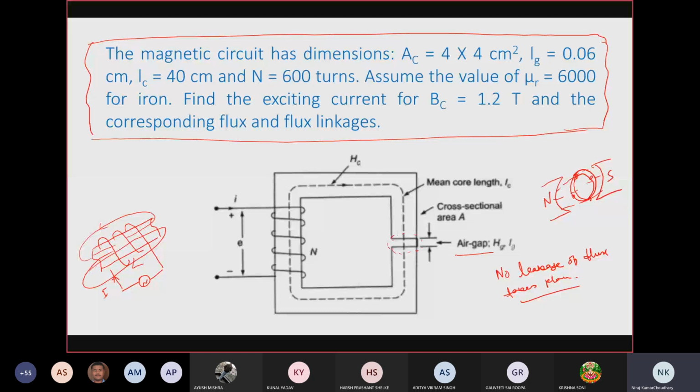through that conductor. So flux will be there, yes, but the amount of flux practically will reduce because air will have a higher value of reluctance than the magnetic material, right? So the value of that flux will be lesser. This is also the definition of reluctance, that which opposes or restricts the flow of flux, just as resistance restricts the flow of current in an electrical circuit. So you have to basically use the same, sir, then divide it into two parts,